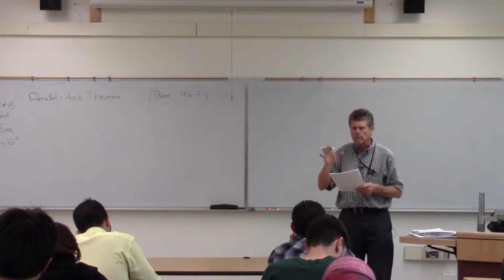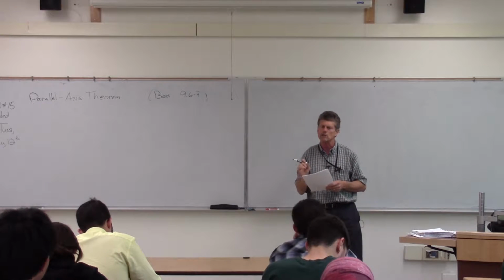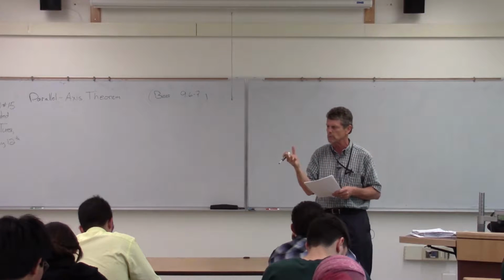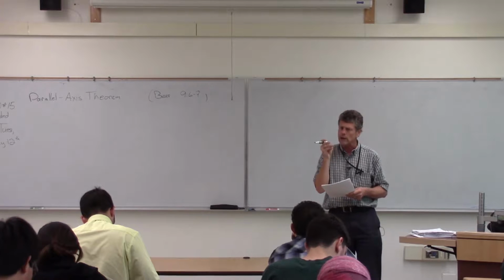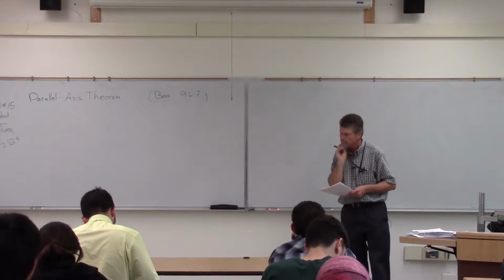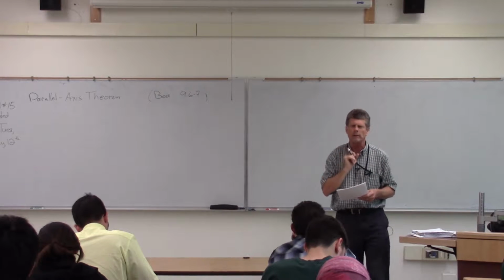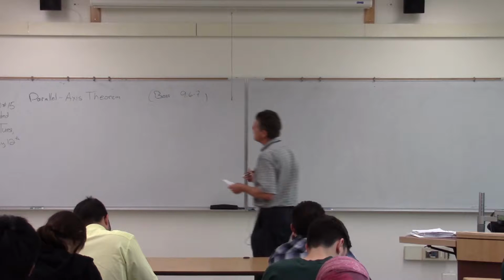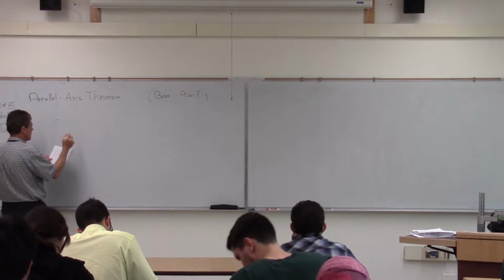Well, we can do the same thing with moment of inertia, but it's a little bit difficult in the sense that when we think about the centroid approach, it was y times A. So it's just very linear. We could do that. Now we got this y squared term that we have to deal with. So what we're going to find is that there is a way of doing it, but it's going to be a little bit different than what we did with the composite approach. So the key thing, what the parallel axis theorem allows us to do,